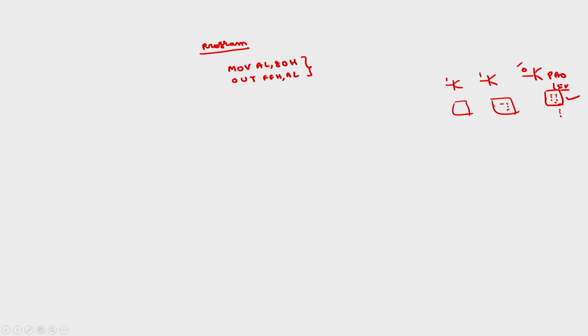Okay. So you have to first send a 0 on PA0 and 1 on the remaining bits of the port. So PA7, PA6, PA5, PA4, PA3, PA2, PA1, PA0. You first send 1 1 1 1 1 1 1 0, which is equivalent to FE. So you take this FE onto this one.